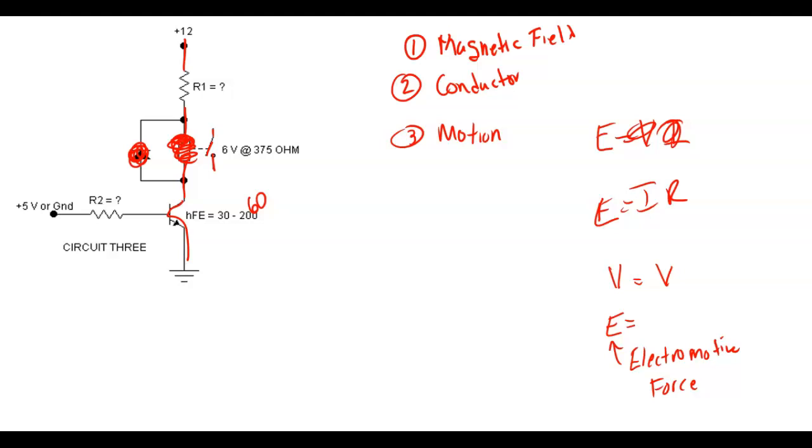So now I have no problem using a 3904, right? You understand that, because if I was to put in a 3904, it's got a breakover voltage of 60 volts, and that sucker generates 90 or over 100 volts, I would wipe out that transistor. Maybe not on the first try, but eventually it's going to get it. As long as it's running, it's okay.